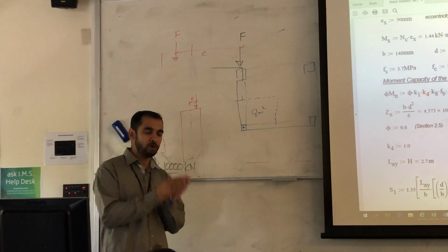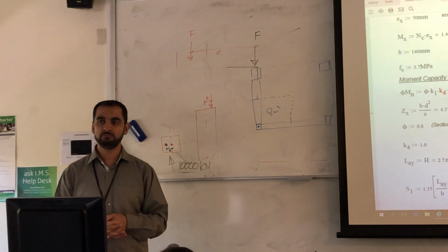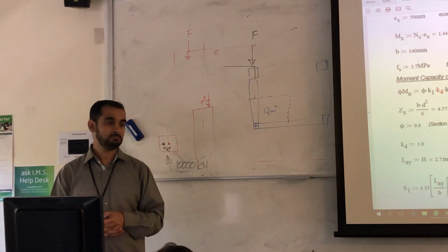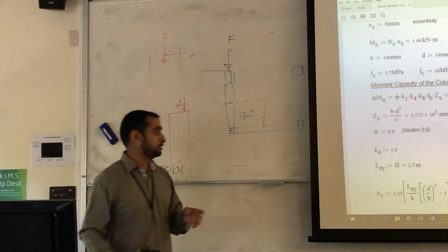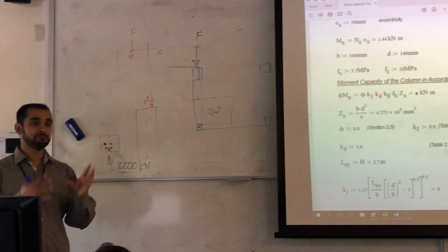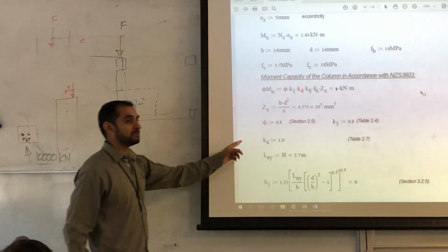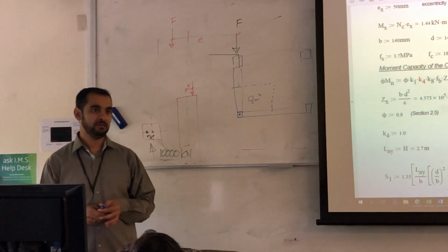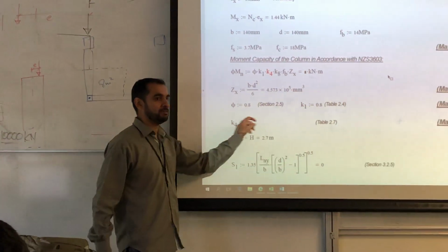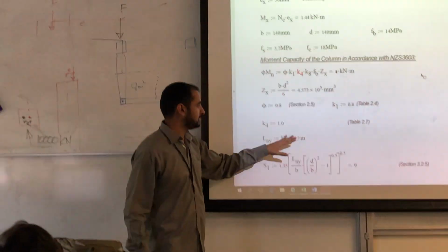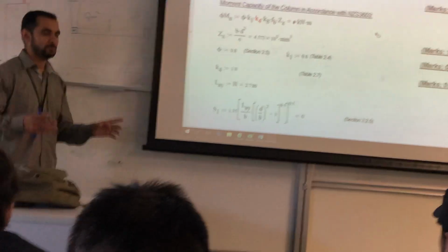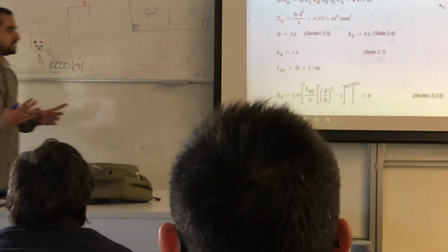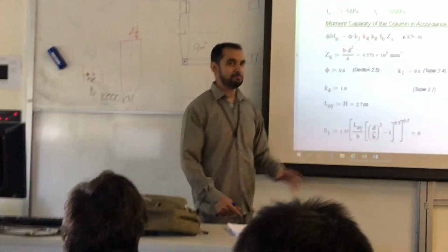If it was multiple members, then what would we have to do? No, I'm talking about K4. You're not concentrating. If it's multiple members, K4 is the parallel support factor, right? So if we have more than one member, then we increase it. And in this case, because it's 140 by 140, it's one solid square section. Why do we increase this?